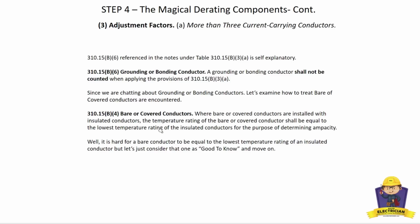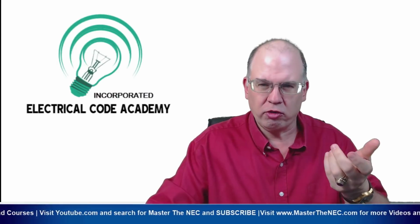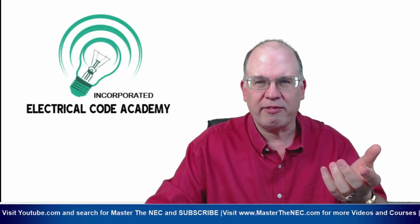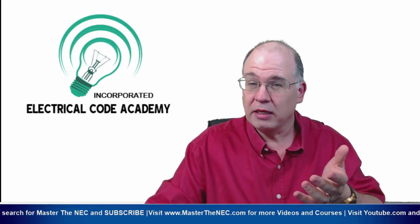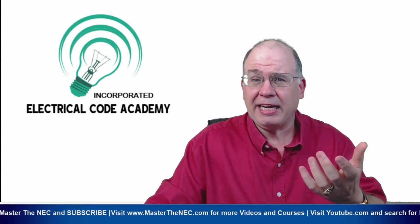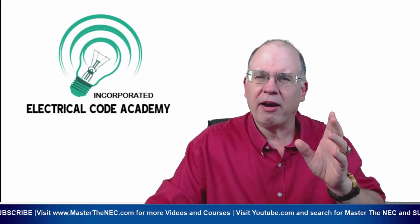All right, so it's just reminding you that the temperature rating of the bare or covered, now I can see where it might apply to the covered, but the bare is kind of difficult to have any kind of rating for, shall be equal to the lowest temperature rating of the insulated conductors for the purpose of determining ampacity. Okay, well, I don't think we have to worry so much about the bare. We do have to look at the covered if it's used, and make sure it has adequate values based on the lowest temperature rating of whatever the other insulated conductors are in the raceway or cable. Probably going to be 90 if we're doing adjustment and correction, so we need to make sure it's equivalent to that.